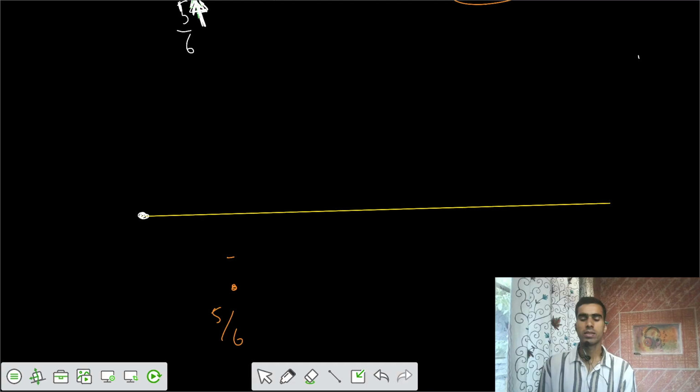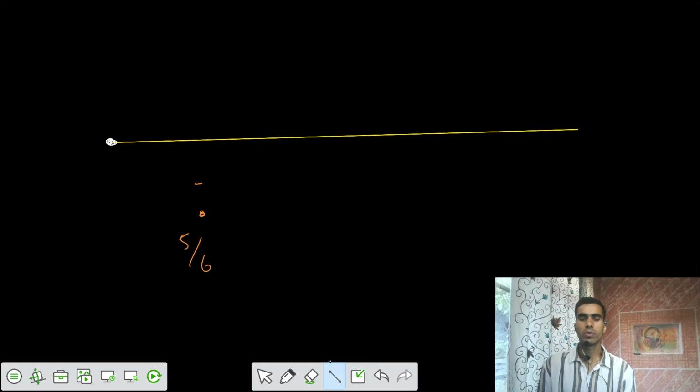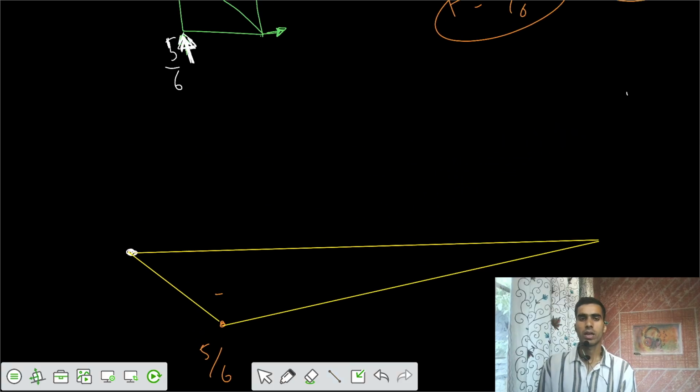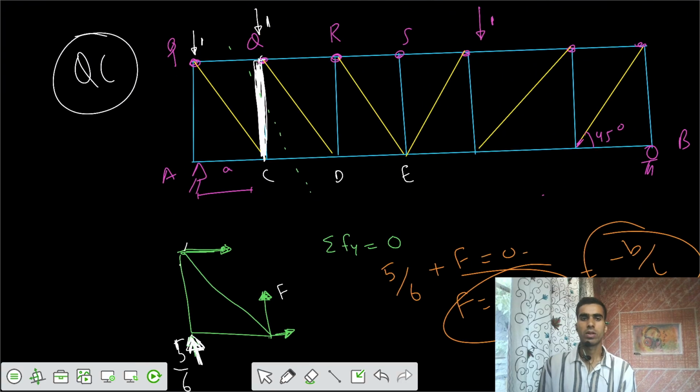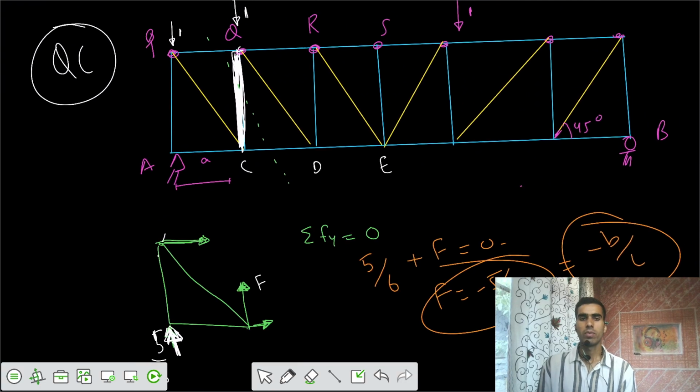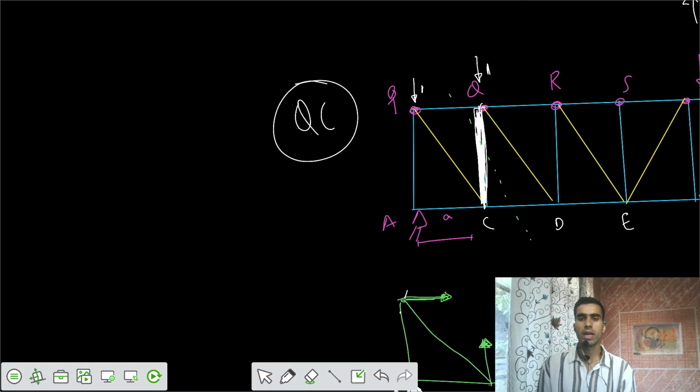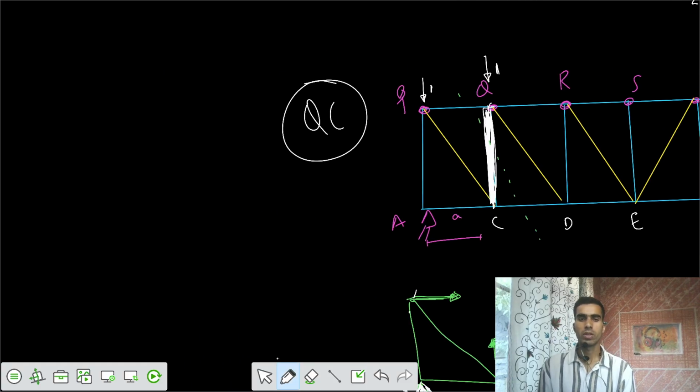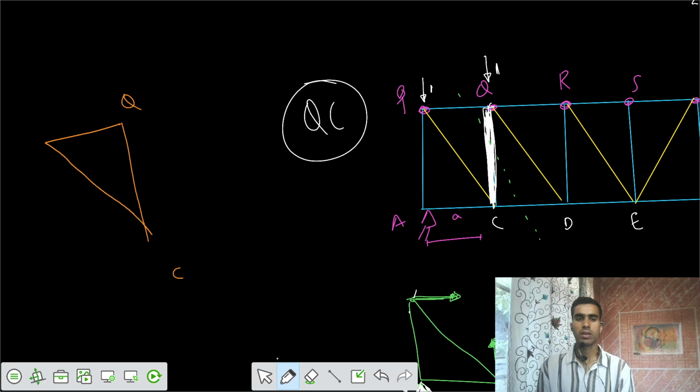Actually, this is the entire thing, you can now join those. Once you have the two critical points, you can join the ordinates. Why are these two critical points? Because where is the member QC? This is your member QC. What triangles is it having? It's connected with two triangles, in this fashion.